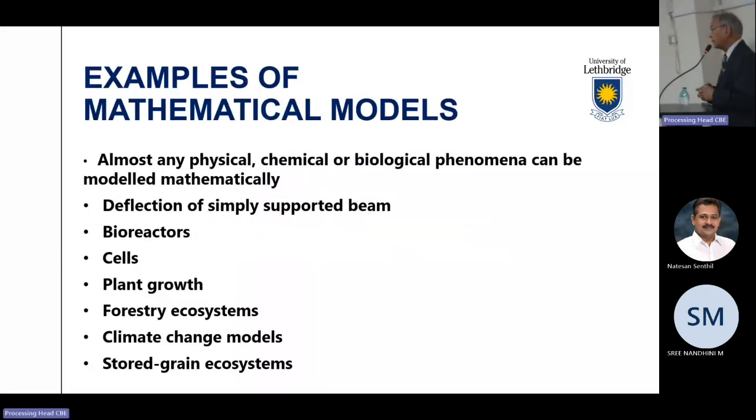You would see there are many systems where mathematical models have been used to advance the field and do the research in those areas. Some of the examples, again, being from an engineering group, you would understand: a simply supported beam is the first thing you take in a statics class, or statics and dynamics class. You try to predict what would be the deflection in that. As you know, the deflection would depend on the width, the depth of the beam, and the material of the beam, because that determines the physical property of it.